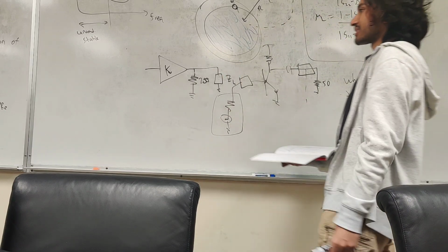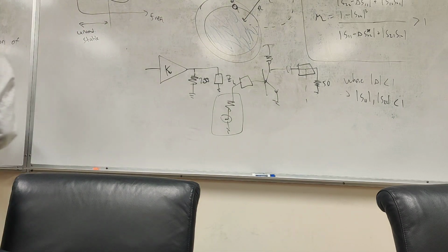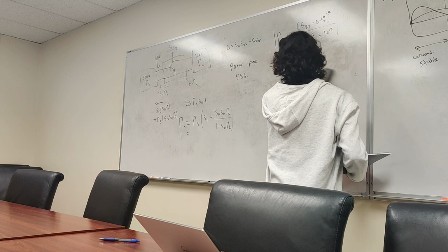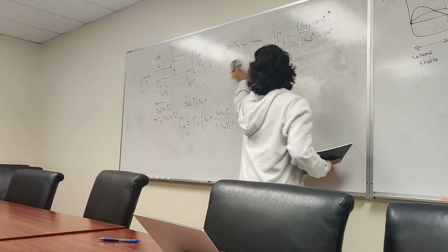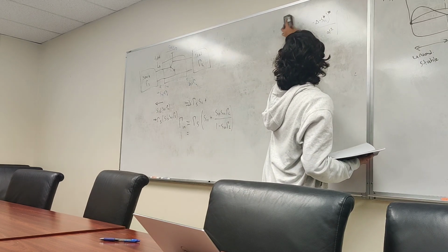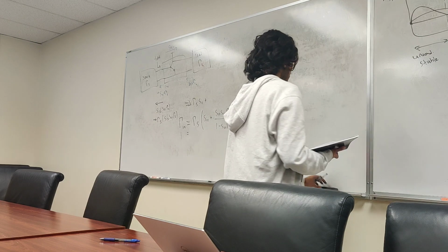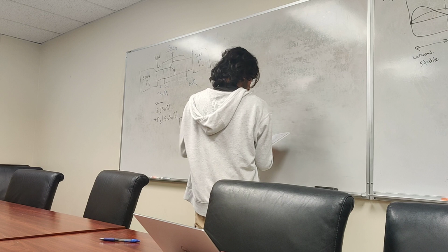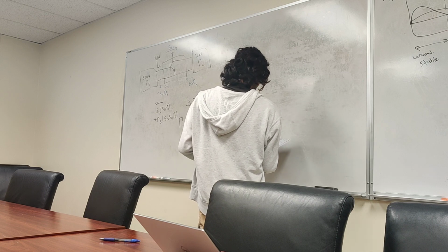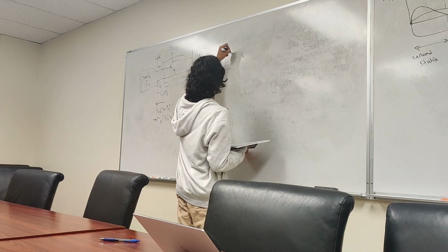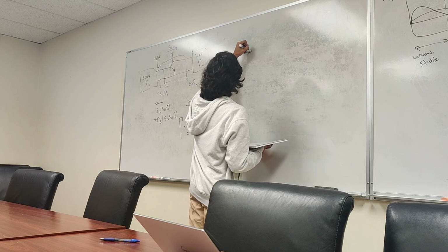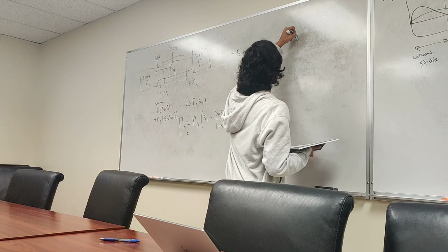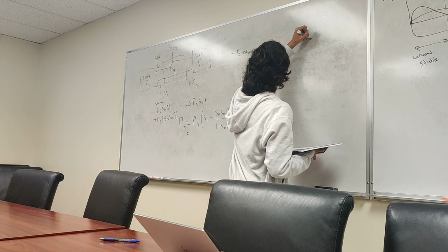The design process is as follows. First we know we pick up a transistor from the market. Hopefully the manufacturer provides us the S parameter data, or we look through the data sheet and figure out what it should be. Okay. And then we try to make our classic common emitters. The first step, ensure unconditional stability.